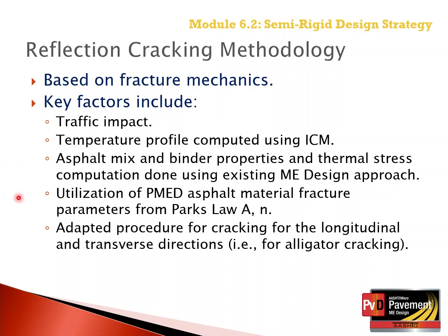It also uses the asphalt material fracture parameters from Paris law, the A and the n parameters that we've already introduced and discussed for transverse cracking in flexible pavements under Module 6-1, and then the adapted or modified procedure for cracking to account for both longitudinal and transverse directions, specifically for alligator cracking.